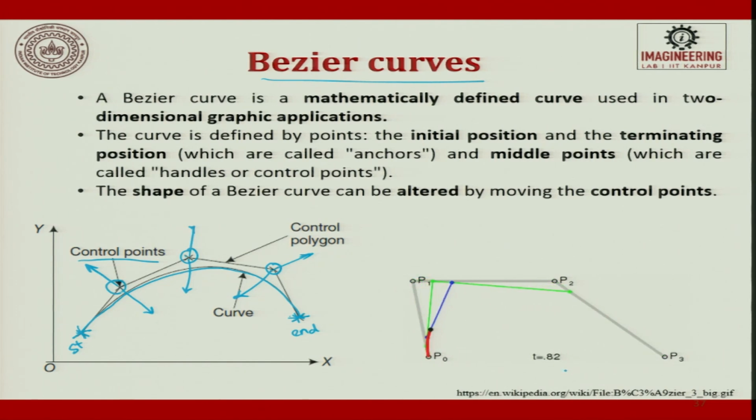So, here is a simulation which is shown to you. P1, P3 are the start point and end point. Now, you see I am establishing various control points by just changing the parametric value from t equal to 0 to t equal to 1. You see how beautifully it follows. Now, it is very clear. I have to use start point, end point, and I will define control points. These control points again into parametric form such that I define a curve.